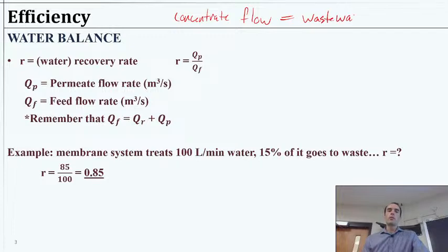So this is water that we are not going to use in any way. And if we sent it back through the membrane, it's just going to bring all those particles and really junk it up even worse. So the whole point is to push these away somewhere else. We can treat them in some manner, whatever's appropriate. Maybe that involves membranes, maybe it doesn't. But the point is it's going away from the membrane, and that can be a fair amount of water lost. So in the case of desalination, we might have to desalinate a bunch of water and make really, really salty brine for this wastewater, the concentrate, right? It has to go somewhere.